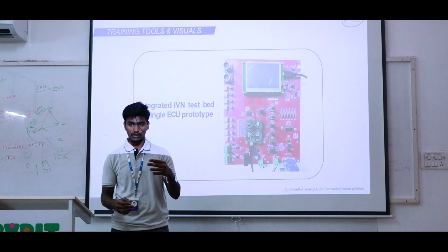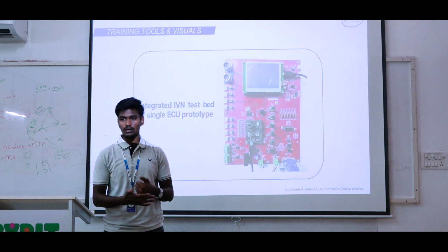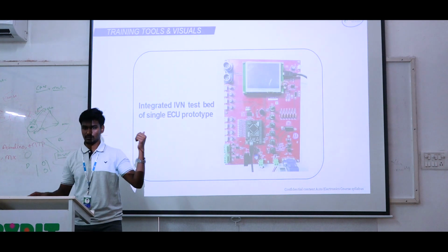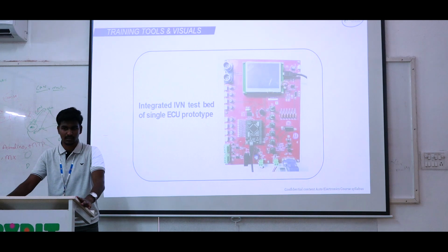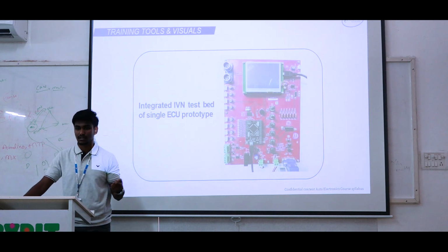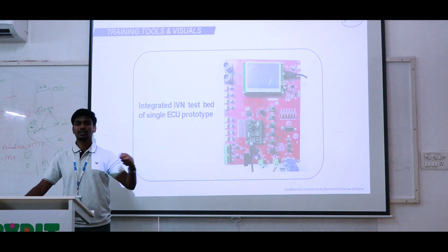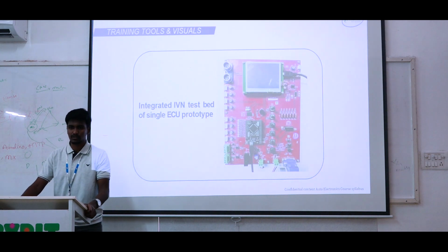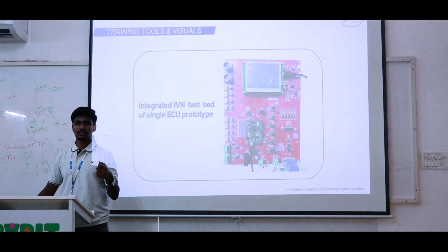Okay, sir, without sensors, can you give some data advantage? Yes, sir, we can use that. That is called simulation functions, restbus simulation. We don't need any ECUs, we don't need any sensors. We can directly generate the signal values. Instead of the real-time one, we can use assumed values, generate them and test the signal. That's also possible. Whenever you enter the tool URL, you can easily get it.